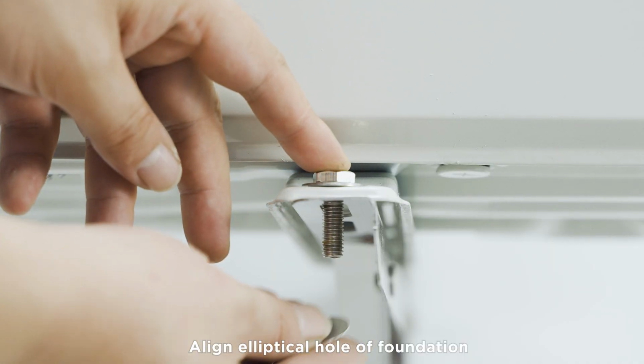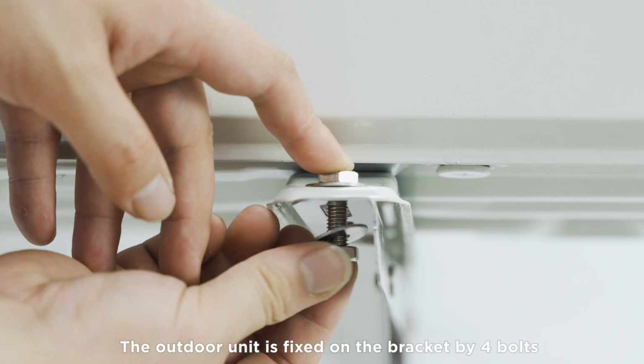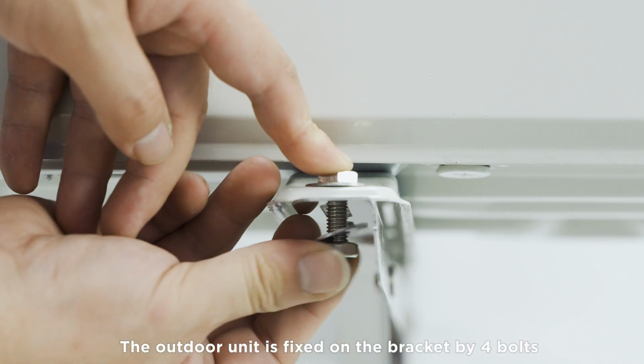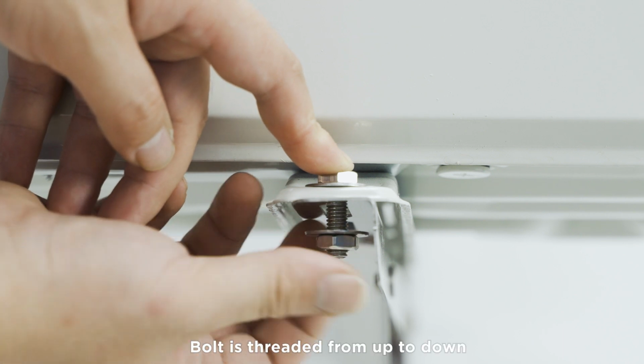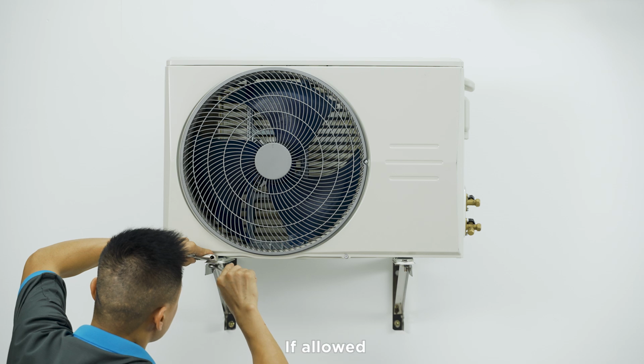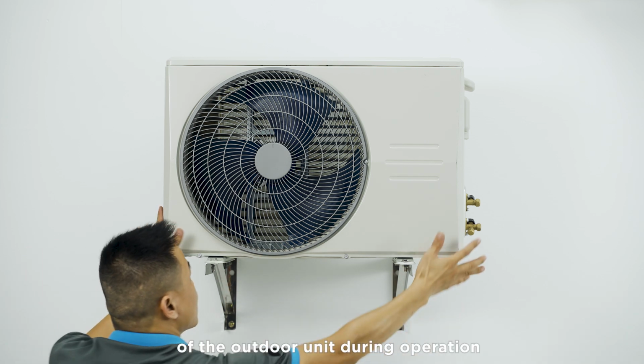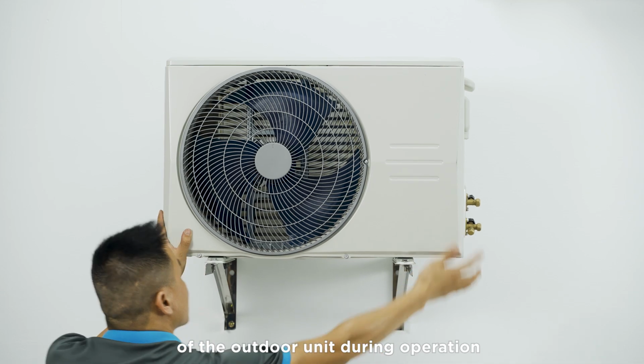Align the elliptical hole of the foundation bolt with the fastener hole of the bracket. The outdoor unit is fixed on the bracket by 4 bolts. Bolt is threaded from up to down and is tightened by adding check washer. If allowed, rubber gasket can be added to reduce the vibration of the outdoor unit during operation.